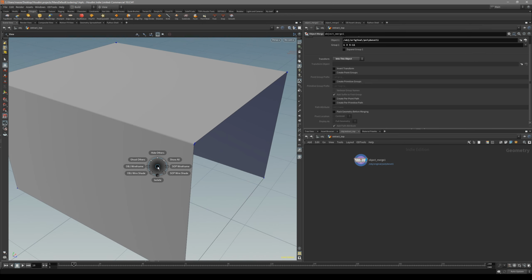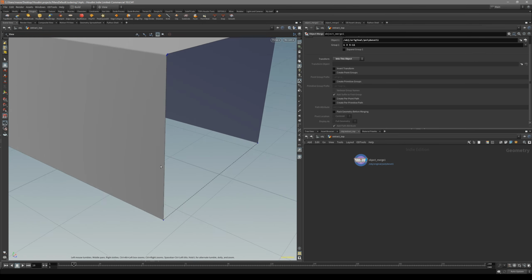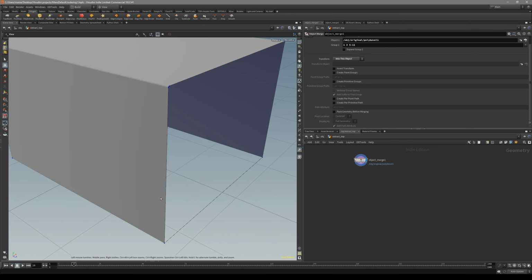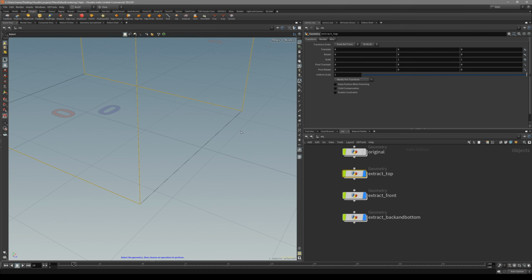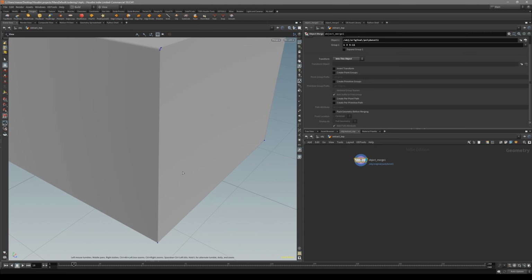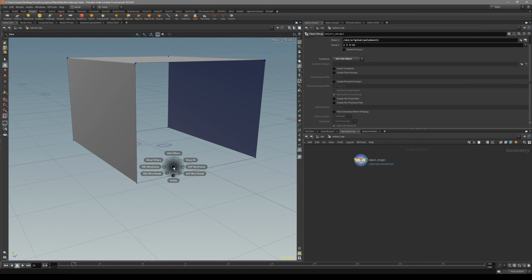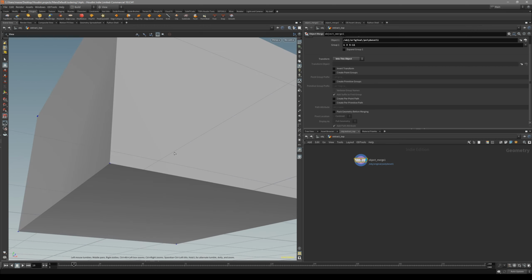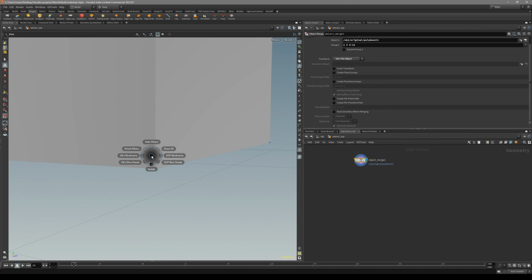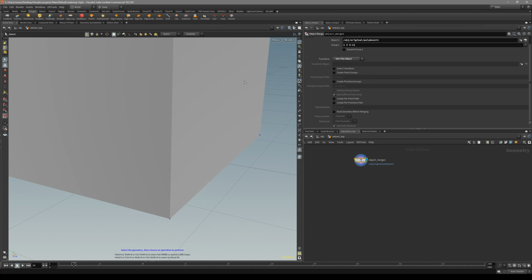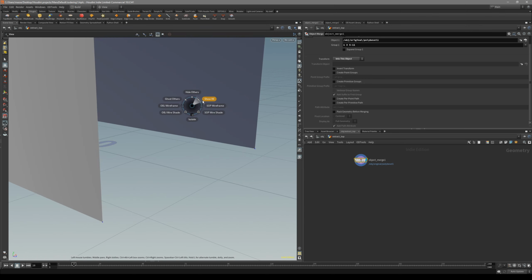So first of all, there's still toggles for the wireframe. But what's cool about this, you can actually toggle also the other. Once you decide in this top board, we can also wireframe the other objects that we are outside of this geo node. So we can toggle the wireframe for the other parts of this geometry, and we can also wire shade other parts of this. You can see that it's basically showing also the wireframe of the shaded model. So basically two buttons are between the SOP level and the OBJ level. And on top of it, there's the same options as in here: ghost others, hide others, and show all.